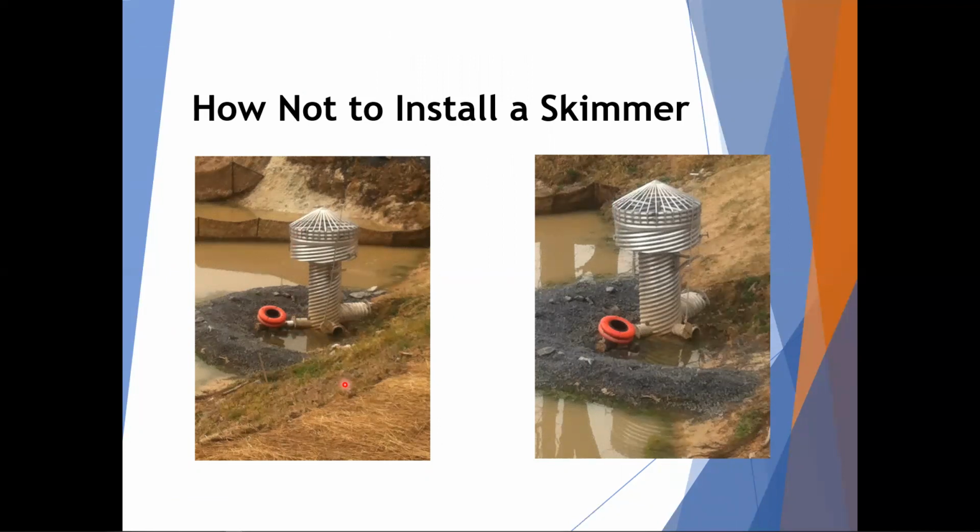You typically don't need your big stone riprap spillway when you have the skimmer. It doesn't hurt to add a little protection to it, but the skimmer's going to float above that in most cases anyway. So you're not really trying to filter water through it, except on the very small storms that maybe come in without much time to settle.